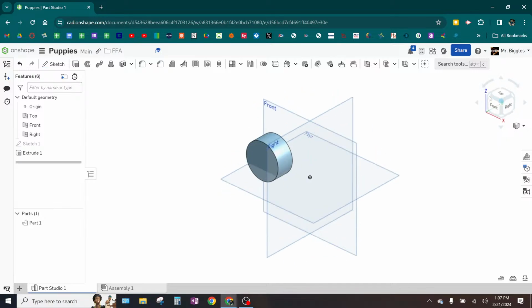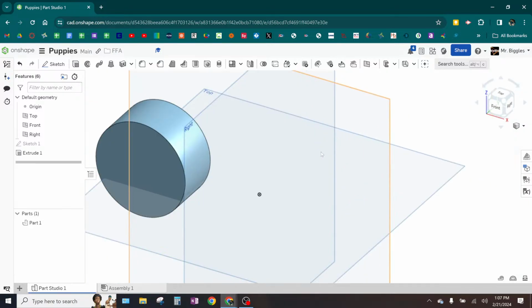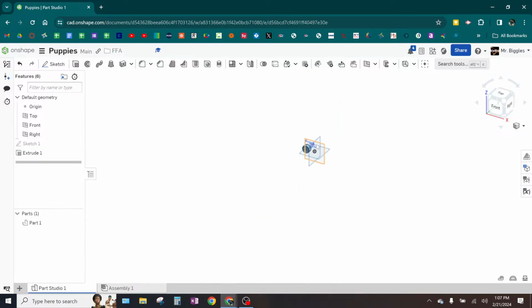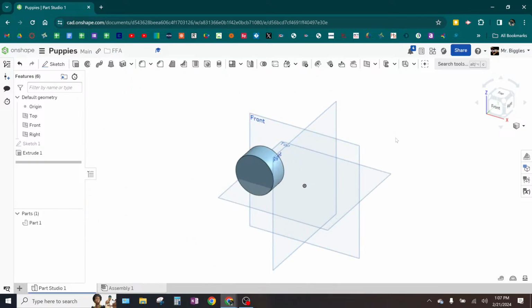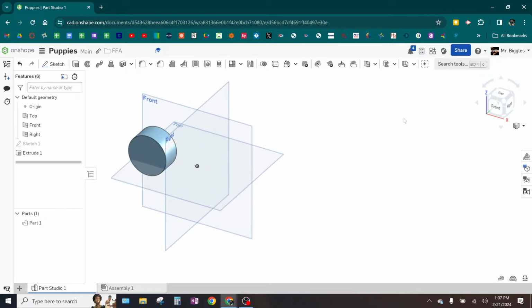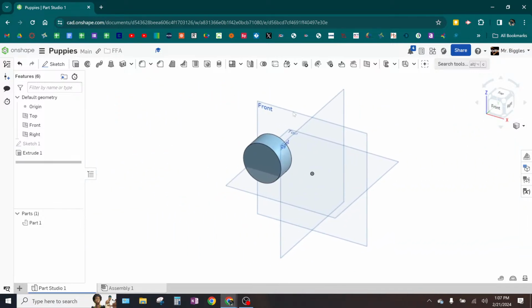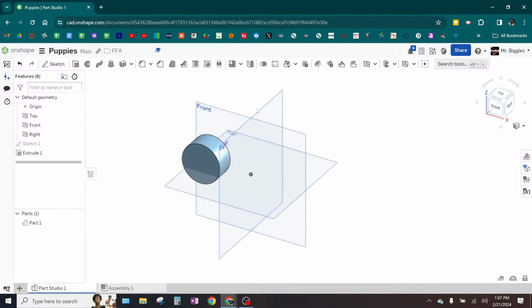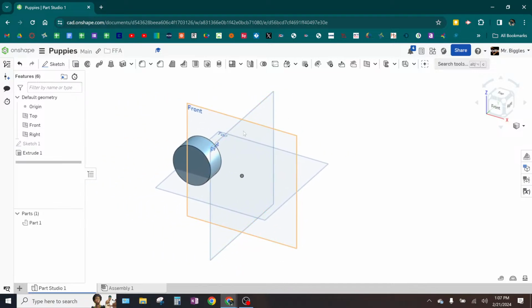You probably have already figured this out, but you can zoom in and out with the mouse wheel. Okay. And then there's something called panning. If you push in the left mouse button, I lied. If you push in the mouse wheel and hold the mouse wheel, you can pan like this. Okay. Do you have any questions so far? So when you're doing stuff, that's the way that you'll change your view. It should be fairly intuitive. I mean, it's similar to other things that use a mouse to rotate your view.